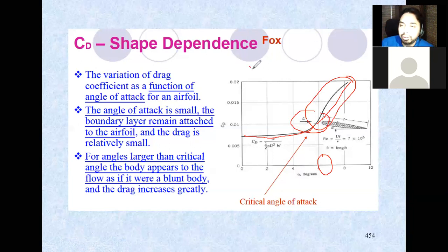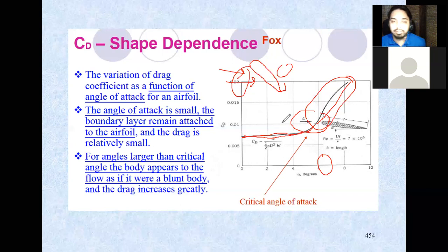As you increase the angle of attack, you're going to have a big pressure difference from here and from here, which will cause the drag of the airfoil. Over here is dominated by the friction drag. But once you get stall, then you have pressure induced drag, which will cause you, on the next one, to lose your lift force, because the lift force becomes the drag force in this region.